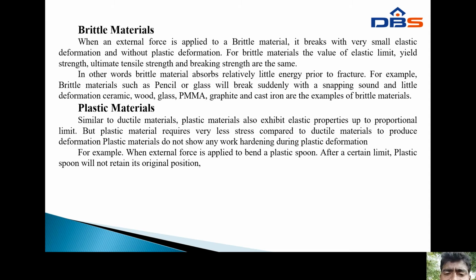For a brittle material, the values of elastic limit, yield strength, ultimate tensile strength, and breaking strength are the same. In other words, brittle materials absorb relatively little energy prior to fracture.